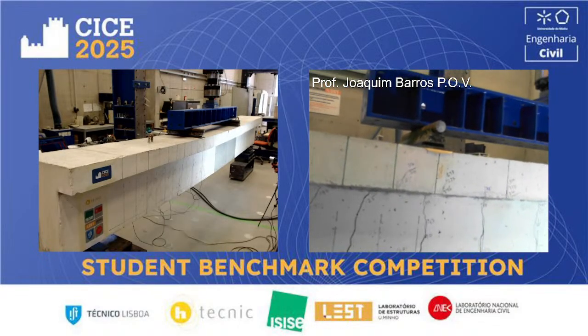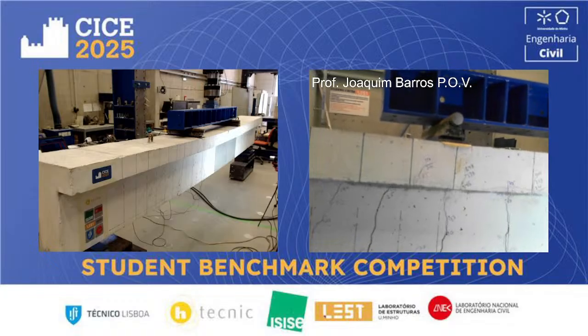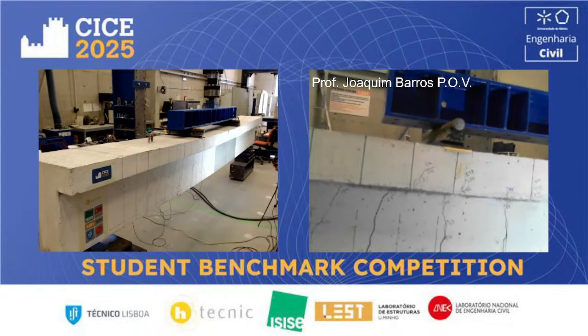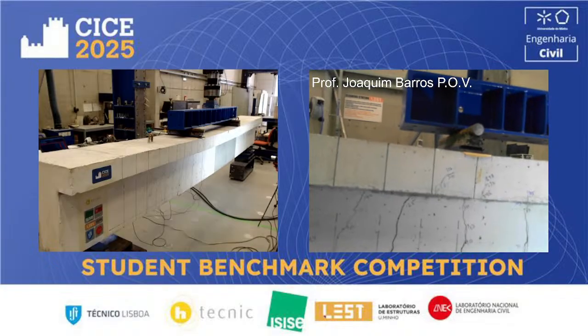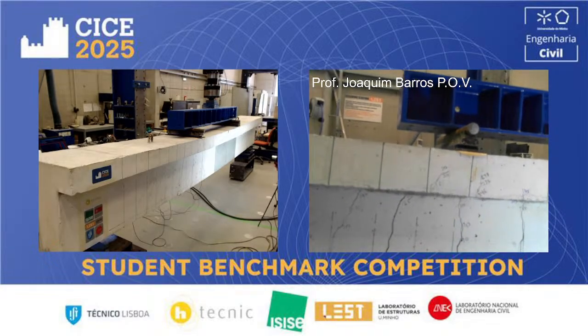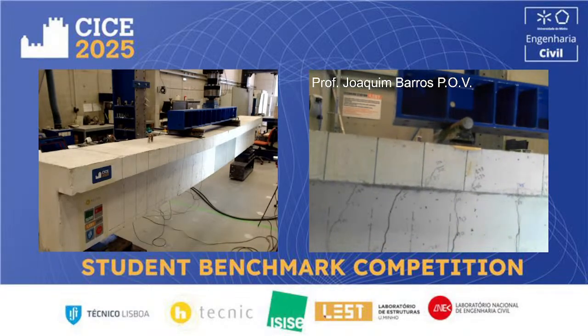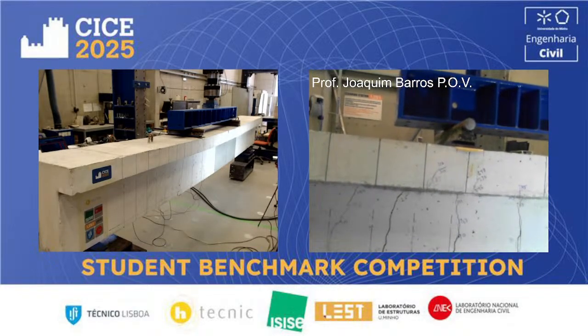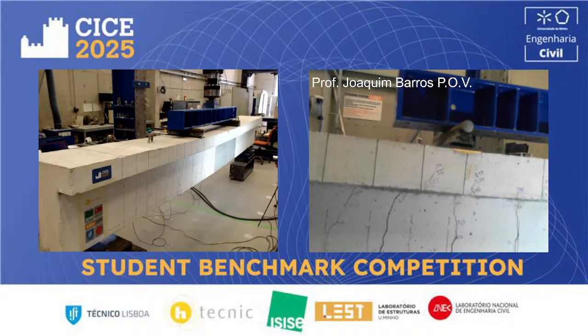So we can see the teeth representation that we have in the bulletin. For the more sophisticated model, the beam is discretized in a series of teeth, crossed by the flexural reinforcement and also by the CFRP.